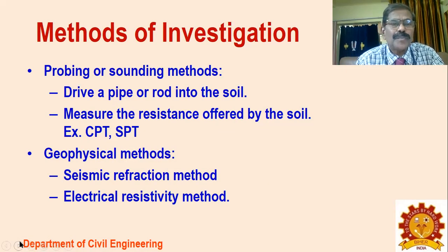Method of investigation: probing or sounding method. You drive a pipe or a rod into the soil and measure the resistance offered by the soil, for example CPT, SPT, things like that. Then the geophysical methods, the seismic refraction method and the electrical resistivity method, are also methods for soil investigation.